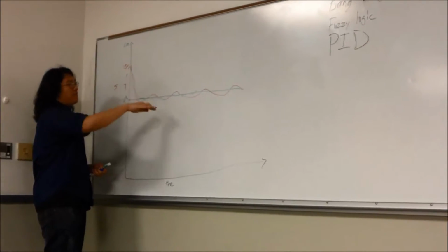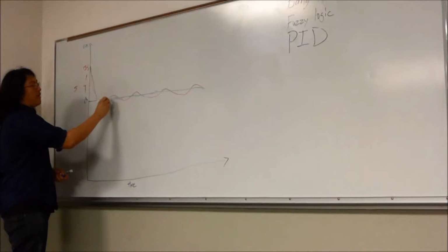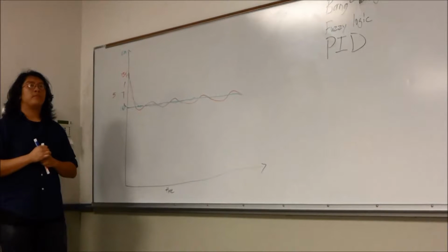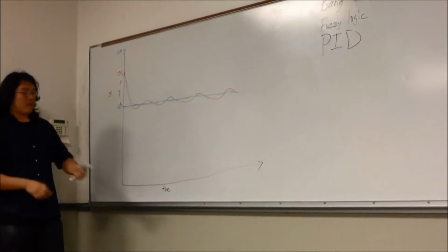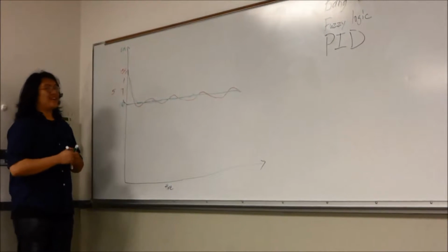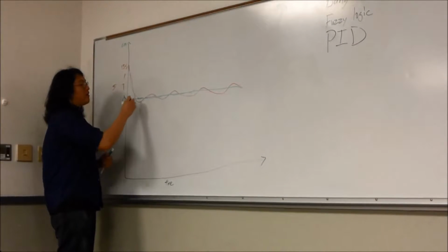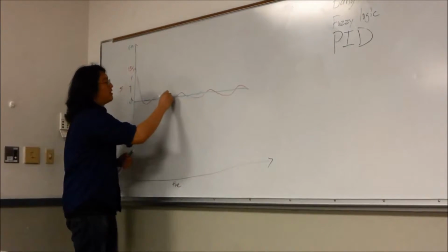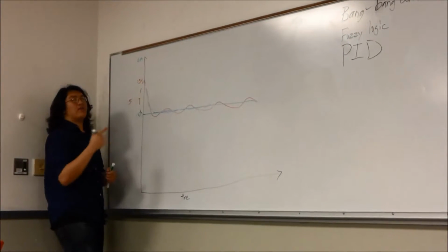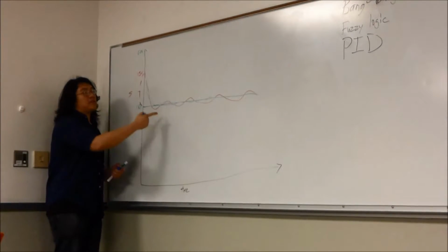As I bounce along the wall, I can take the integral of my error. I have to change this a little. The Region 5 robot is on a hill. There's gravity happening, and so no matter how hard it tries, it needs to exert a little extra motor power in order to get on the line, because it's going to sit a little off the line, and it needs this error term to drive it up against the hill so that it's still maintaining position. This can be corrected by an integral term.